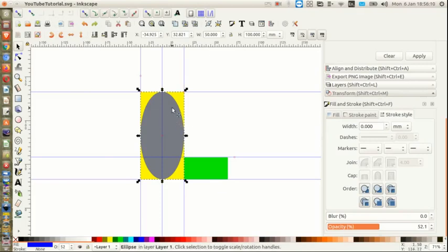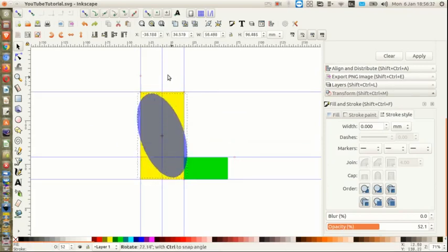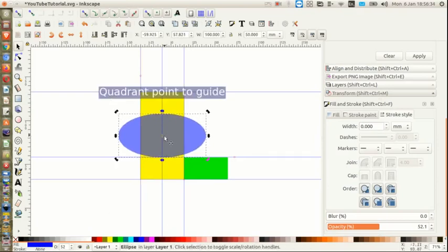Okay, right, if you click an object using the Select and Transform Objects tool, you get these arrows here which enables you to change the size of an object. If you then click it again, you'll see that these arrows change to rotation things, and they allow you to rotate the object about its centre, which is this little cross here. And by default, the centre of an object goes to the centre of the bounding box, and the bounding box of an object or path is this rectangular thing here.